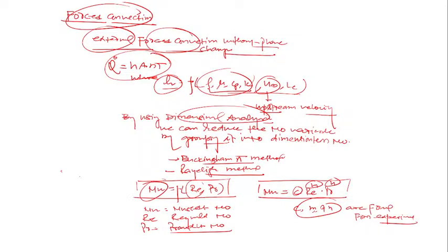But before that, the important thing is that this heat transfer coefficient, or indirectly the Nusselt number, is strongly influenced by the Reynolds number. And the Reynolds number depends upon the type of flow condition, laminar flow or turbulent flow. That is why, indirectly, it depends on U infinity, or U here, because we are talking about external forced convection.